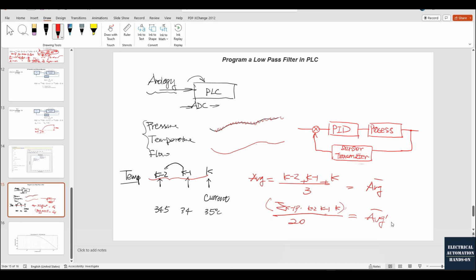And if your system has 100 analog signals, you need to do this average for each. You can imagine that you need to shift the buffer, typically using a for loop, and you also need to calculate the sum and divide by 20. Sometimes division is not good. In case you forget the denominator and accidentally your denominator is equal to 0 at the initial status, then your system will stop because the calculation divides by 0. So this is a potential issue.